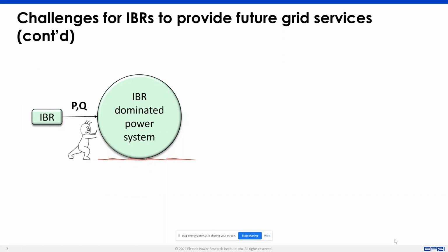Electrically, they are both going to influence each other's position. It's not going to be a scenario where the position of one resource electrically is fixed and it's only the other resource that's moving, but they're going to influence each other. And in that closed loop relationship, where they are going to be influencing each other, that closed loop relationship can become unstable when you have an inverter-based resource control.